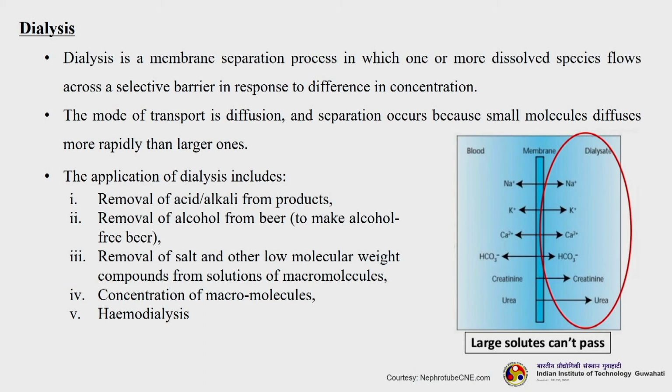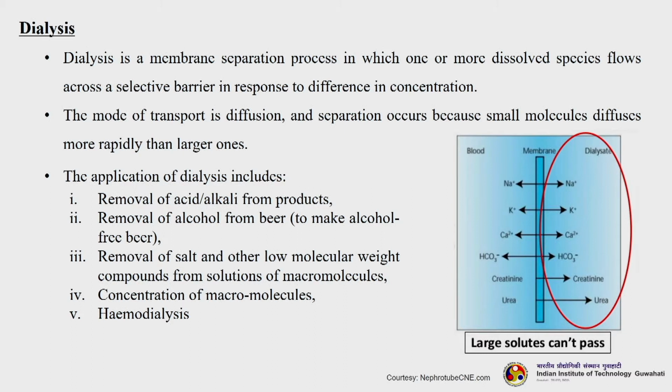So, the next process is dialysis. Dialysis is a membrane separation process in which one or more dissolved species flow across a selective barrier in response to a difference in concentration. Please remember that dialysis is a concentration driven membrane separation process. The mode of transport is usually diffusion, and the separation occurs because small molecules diffuse more rapidly than larger ones. It is quite understood that the diffusivity of smaller molecules will be higher than that of larger molecules.